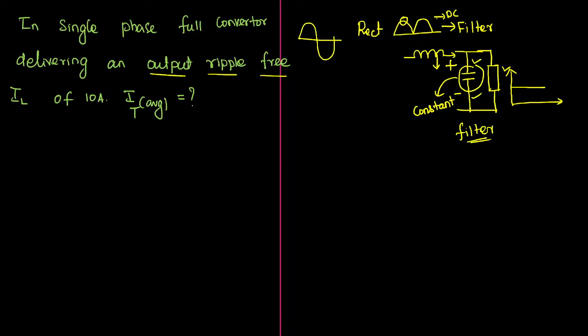இது என்ன பண்ணோம்னா, capacitor வந்து இந்த pulsating charge எடுத்துக்கிட்டு full charge ஆயிடும். Once it is fully charged, then it will try to maintain the constant voltage across the load, like our Zener diode. That will also do the same thing, but that operation will be different. That will also be used for voltage regulator. Voltage regulator means we are trying to regulate the output voltage constantly. That is filtering action. Like that, இந்த மாதிரி பண்ணாங்க அப்படின்னா என்ன நடக்கும் அப்படின்னா, output will become ripple free. The nature of the output voltage will become ripple free.